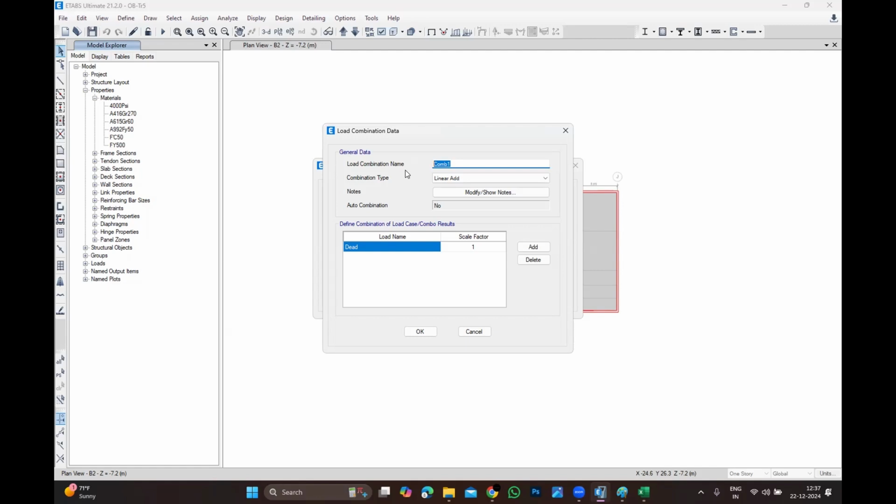From which floor onwards, because even if you're providing an outrigger, you need to know from which floor I need to start with the outrigger. It is not that, sir, I provided the outrigger on the top roof or upper roof, or I provided some bracing. 100% sure you will not be controlling the drift. Then you have been understanding the concept in a wrong way. You have a problem in the drift from some floors, either 2/3 or 3/4.